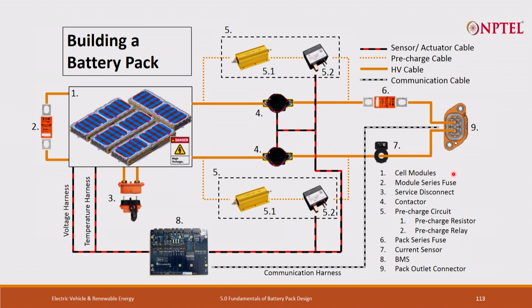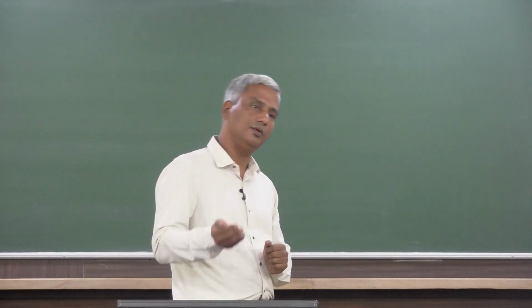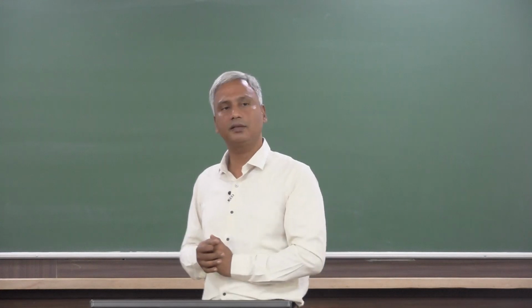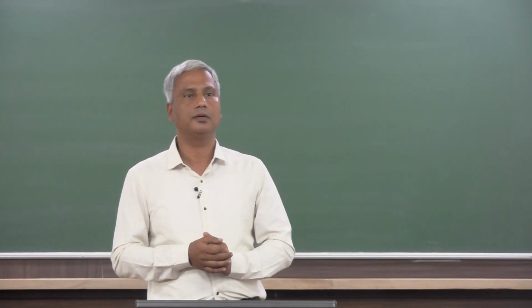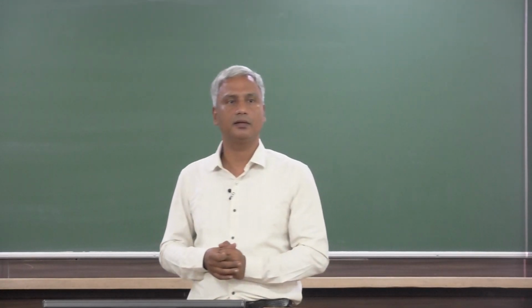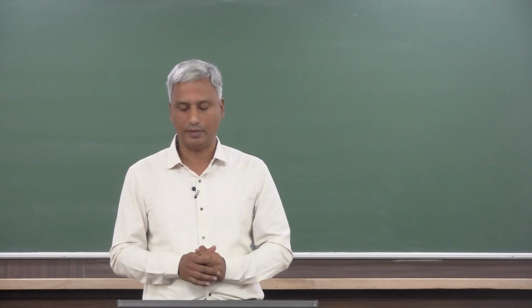If all the things are satisfied, then what do you do? These are all performance testing. Then you start reliability testing. When we say reliability testing, you run for thousands of kilometers. If none of the problems are recurring, you are okay. Wherever you find some problem, you come back, rectify that problem, and start rerunning. We do various tests of AIS standards, ISO standards, SAE standards to confirm the reliability as well as performance.